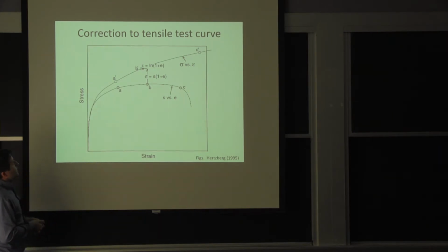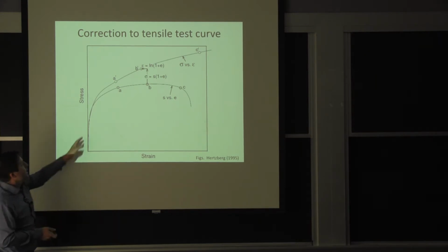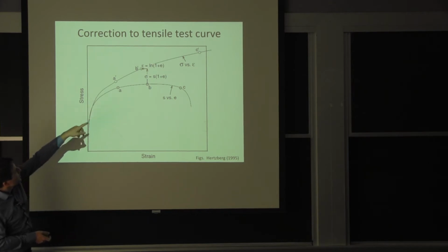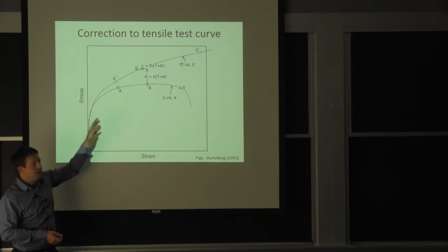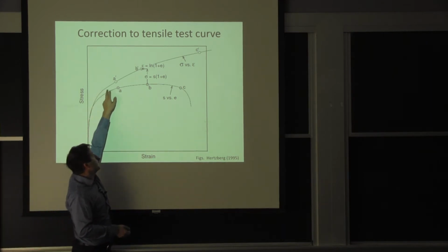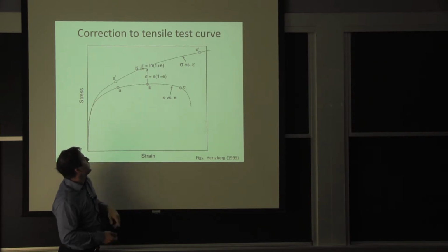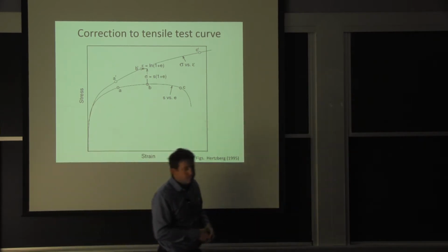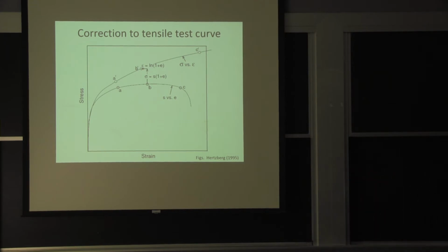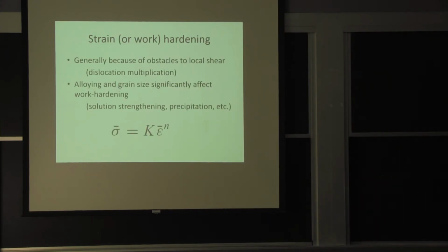So what we do typically is we use a power law regression, and we extrapolate. So where you get the C prime is not really by working with the C, it's just extrapolating the best fit curve that we can get between the beginning of plasticity up to the B value, the peak there. So why are we doing the regression?